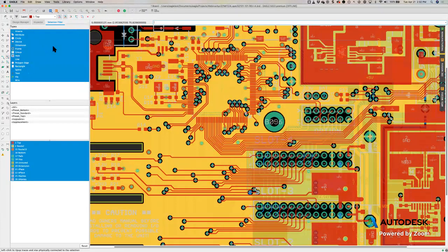Okay. So the last option on the rip up says all visible polygons. It's going to get rid of them. It's not going to delete them. It's just going to get rid of them, that way they go back to the outline form. As you can see, polygons in the outline form are visually identified by those little hatch marks, those hatch lines. Those are the different polygons.